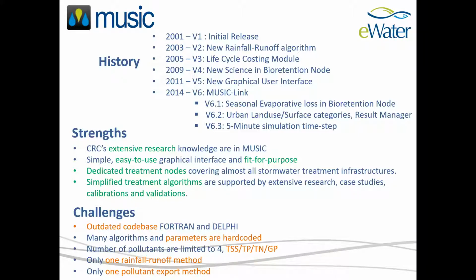The main strength of MUSIC is its extensive research, significant calibration and validation through our CRC. It is easy to use and fit for purpose software. It has a dedicated treatment node with a simplified treatment algorithm. But there are challenges in MUSIC Classic, such as an outdated code base, and parameter algorithms are hard-coded within the code. The number of pollutants is limited to 3, also 4. Single rainfall runoff method, single pollutant export, and etc.